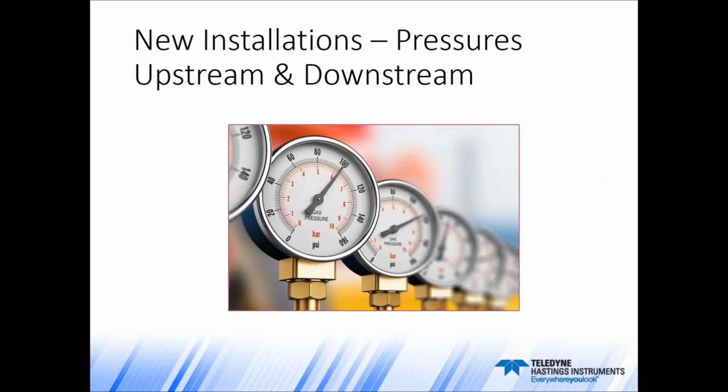Okay, remember the two things we're after with a new installation is to make sure we have accurate flow readings and that we are getting stable flow control across the entire flow range. Earlier, we said that we select the valve's orifice based on the user's desired conditions, that is the flow rate, the gas type, upstream and downstream pressure. On many MFCs, these conditions will be marked on the side of the base. So pressures, like upstream and downstream pressure, are very important. If a flow controller is sized for a certain upstream pressure and that pressure is not available, then the flow controller may not be able to reach full scale.